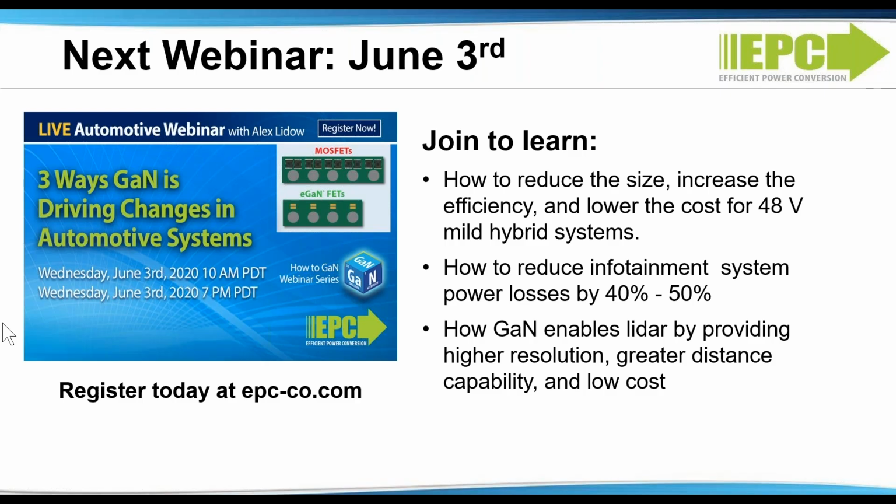The reason for that is the avalanche of a 100 volt device is probably somewhere around 250 volts, and that has to do with some of the failure mechanisms of GaN. As time goes on and our technology gets better, you will see higher performance devices, and maybe eventually we'll also have avalanche ratings. In the meantime, by having a chip scale package, keeping a tight design with low parasitic inductances, your overshoot can stay inside that window very easily.